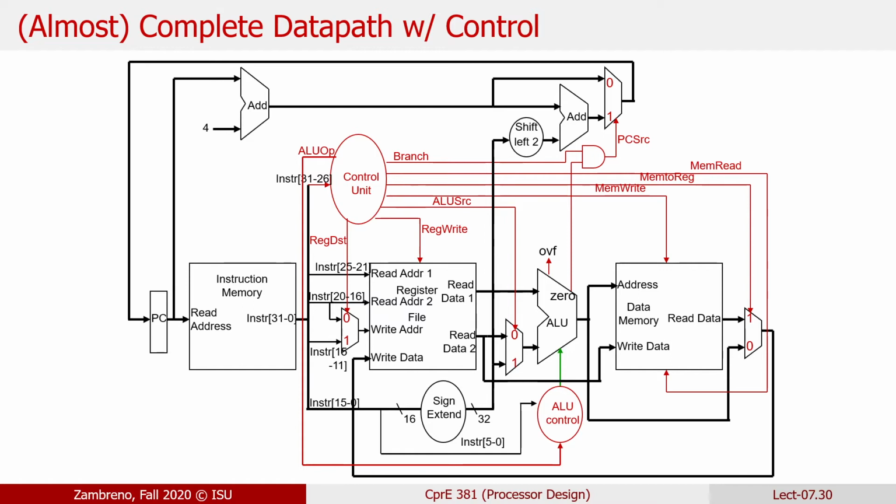We're going to have support for 1,000 or 2,000 instructions in our instruction memory. So we can initialize the program counter to a really high address. We're still only going to be grabbing the lower-end bits for our read address, just like for lab 4, where we had to do the same thing because yes, it's a 32-bit address we're generating. We don't want to have to simulate 2 to the 32 bytes of memory. We could, it would just be exceptionally slow. Everything's slow enough this semester.